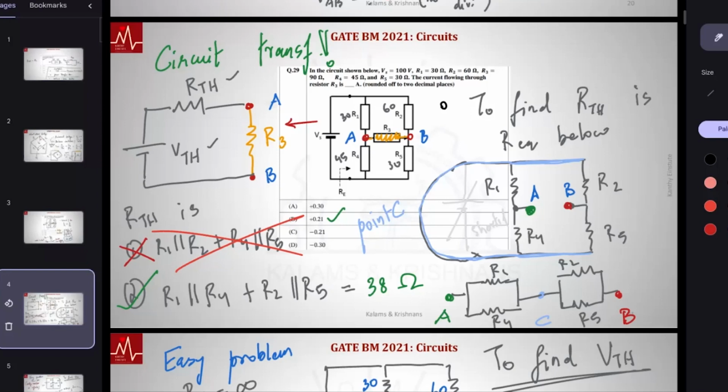See, the resistance is kind of finite, the current is too small, but that would really depend on how balanced or imbalanced the bridges are. In fact, in the given scenario, they have made a diagonal change, right? Let's say all four are 30, 30, 30, 30. They have increased this side by 15, they have increased this side by 30. They have created an imbalance, right? 30 plus 15 here, 30 plus 30 there. There is an imbalance, because of which there is a current flow. So notice they are creating an imbalance at diagonally opposite sides, so that there is imbalance. So negligible and zero are different.